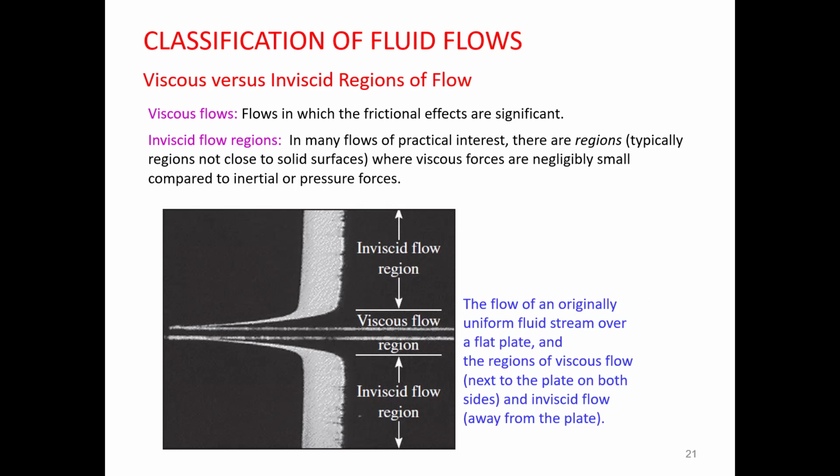flow. In many flows of practical interest, there are regions where viscous forces are negligibly small. That kind of region we can call an inviscid flow. In this region you can see the middle part is a viscous flow region, and neighboring this viscous flow region, this is an inviscid region.